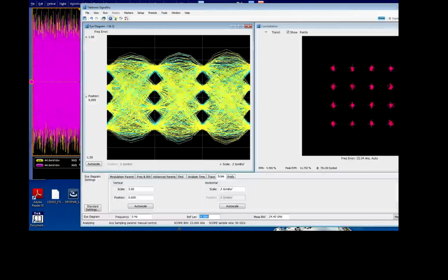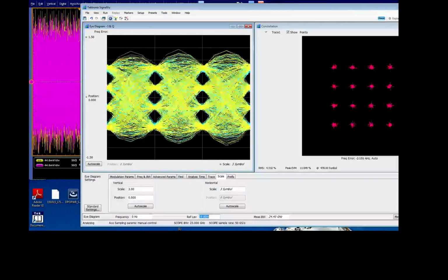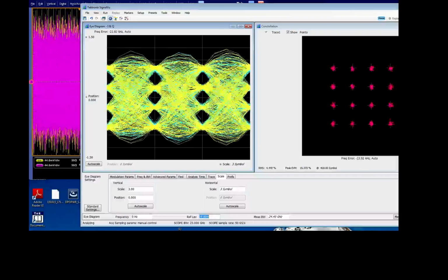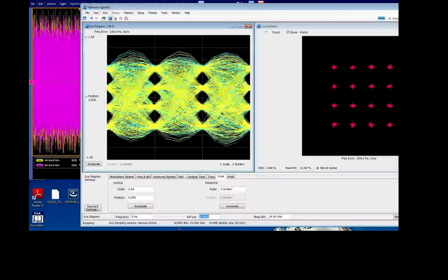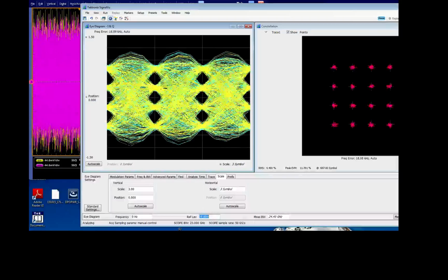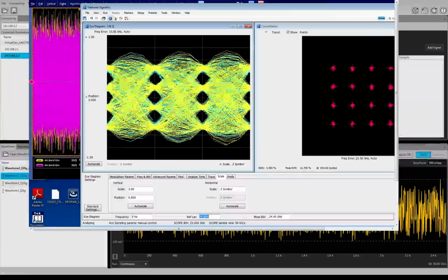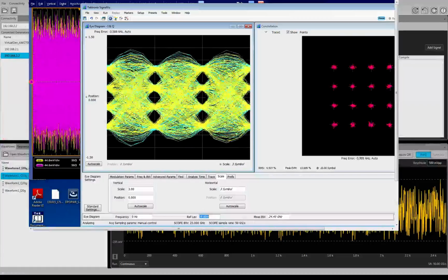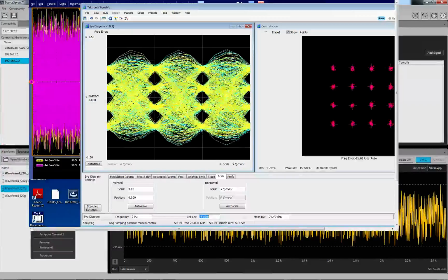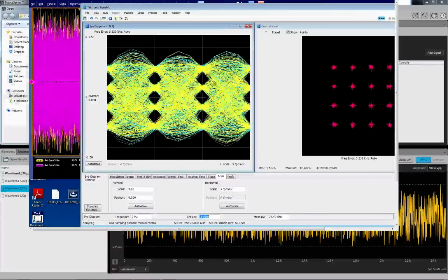The last thing I would do is change the correction filters again, which have a 1 megahertz resolution in the band instead, to see if we can improve it a little bit more. So we go to Source Express and try to do this. Here we are. Load it. And we're going to do this one so you can actually see what I'm doing this time. So I go for the Q waveform, apply corrections, and I have Q fine.